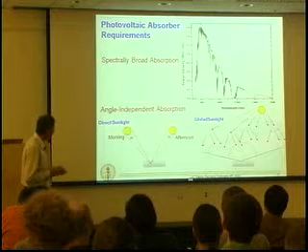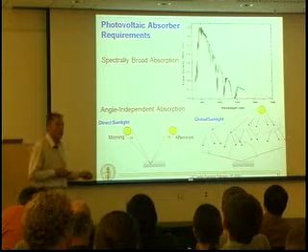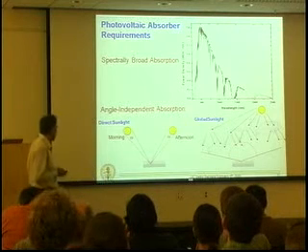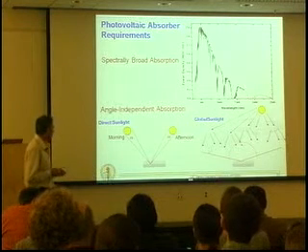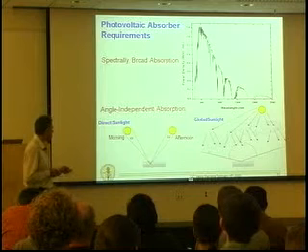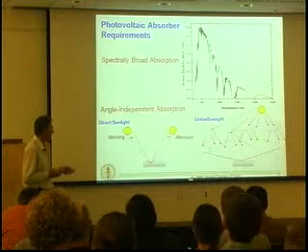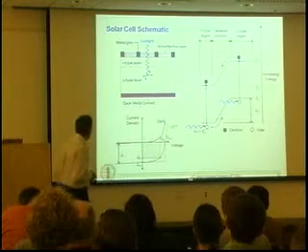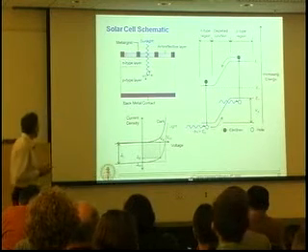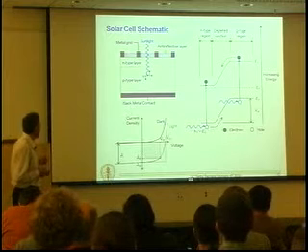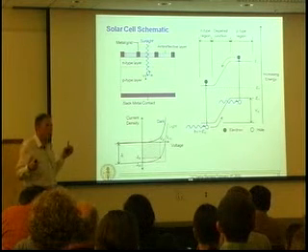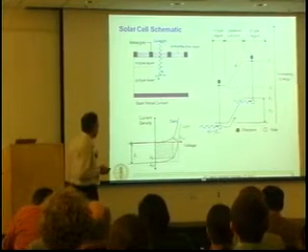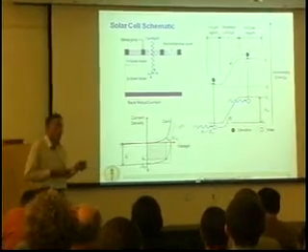One way you can cope with this, if you insist on always having the same incidence angle, is to track along with the sun mechanically, but we don't want to do that. We'd like to fix the photovoltaics as flat plates and have them couple light in over broad incidence angles. Of course, a solar cell has two jobs in life. It has to absorb the light, and it has to extract the photoexcited carriers into an external circuit, which then does work on some external load.